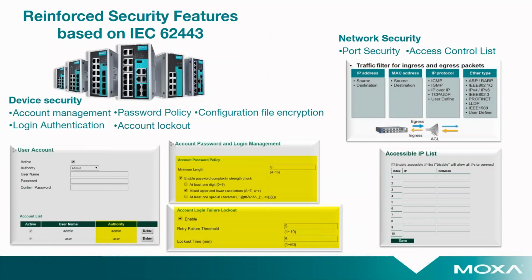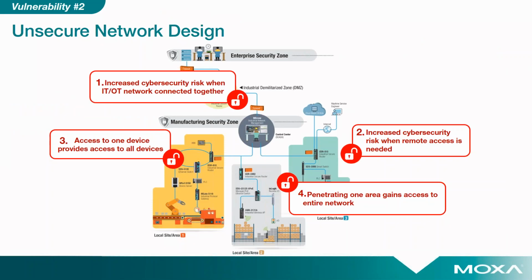All right, so for that, we reinforced our E-series switches with the account management, the password policy, encrypting the configuration files, login authentication, and even account lockouts, right? Makes it very easy. And also you can control what IPs and what type of traffic you want to allow to communicate with the device. Just because you can connect to it doesn't mean I want you to be able to access anything. I want only Modbus communication to hit this specific device behind that switch, right? So it's a really great way to secure the network by adding that port security and that access control.